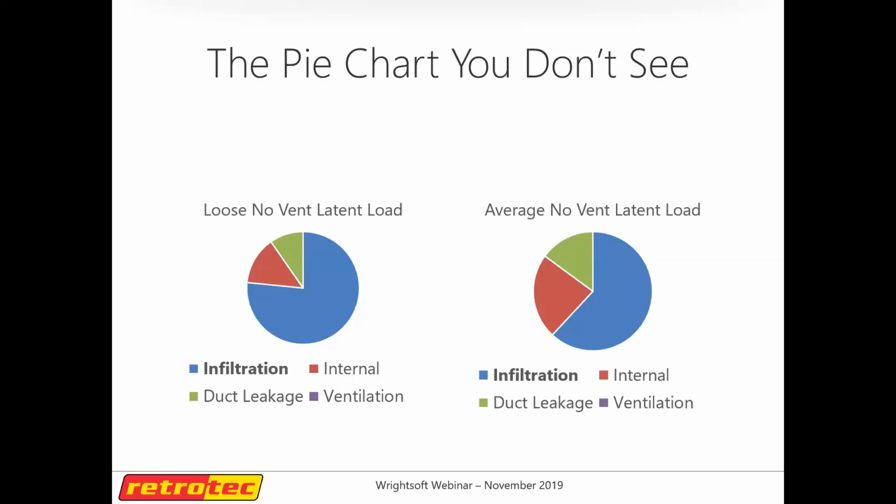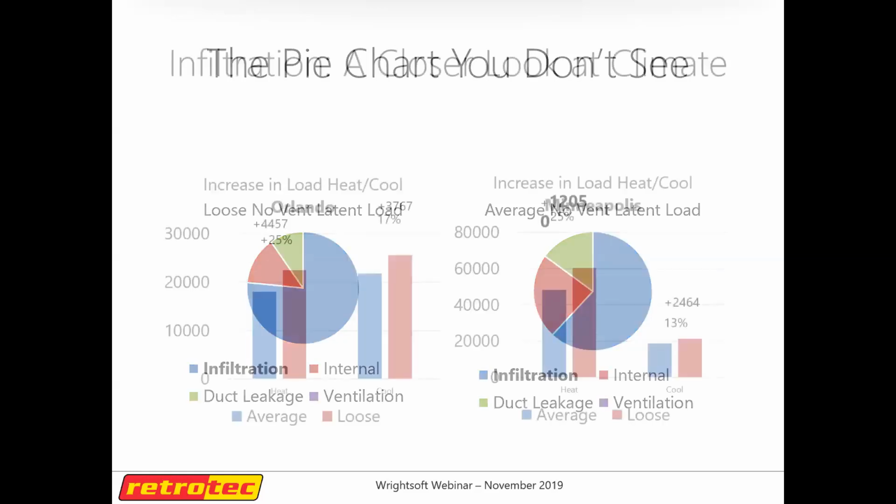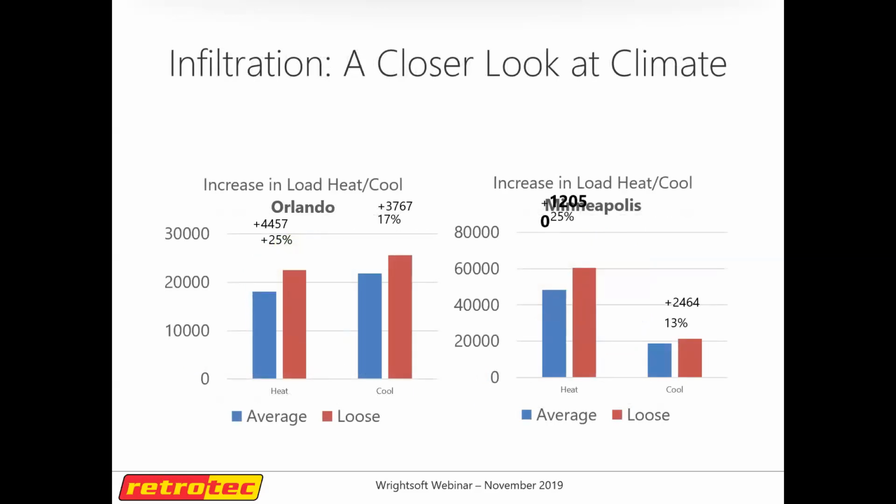And that's why you have to size an HVAC system correctly. It's because moisture removal is extremely difficult, right? Heating is easy. Any idiot can do heating. You want to heat, you throw more heat at it. I'm not saying you should oversize a heating system. There's reasons not to oversize heating systems, and we'll get into those.